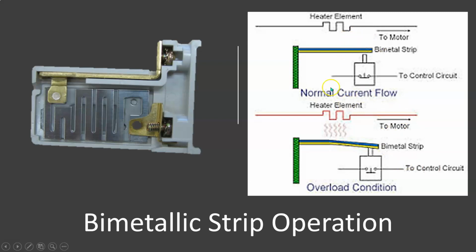Obviously, these ones take time to reset. The bimetal strip has got to calm down a little bit and go back, be nice and straight, which is going to then close your contacts and allow you to start that motor again. So that's this guy right here.